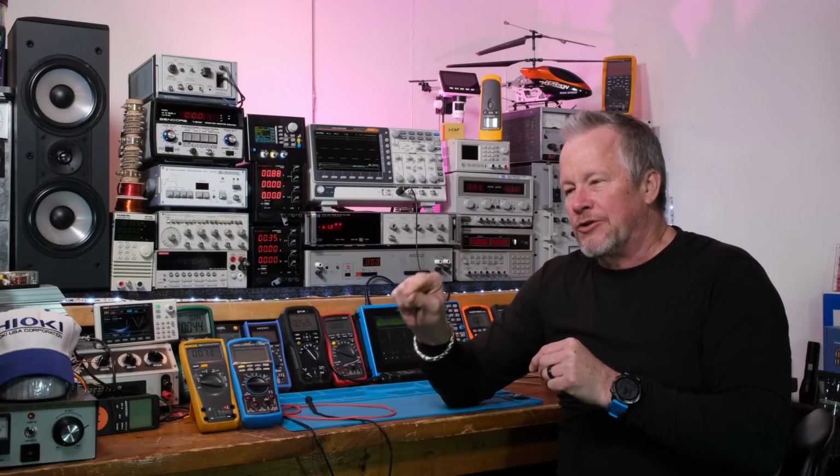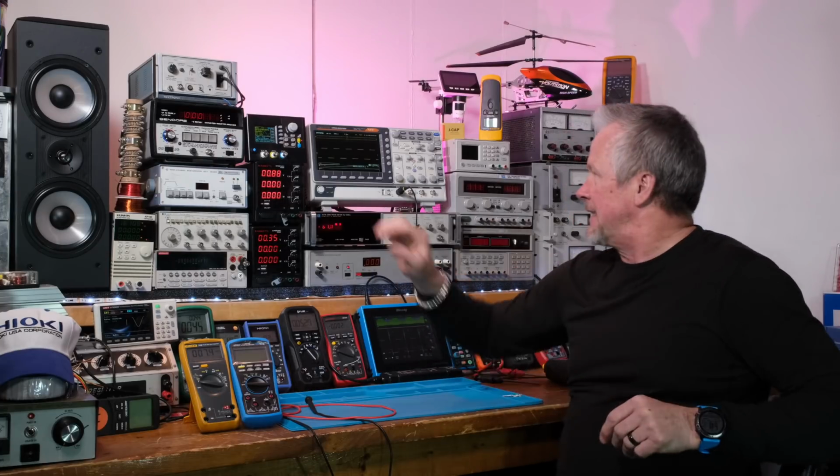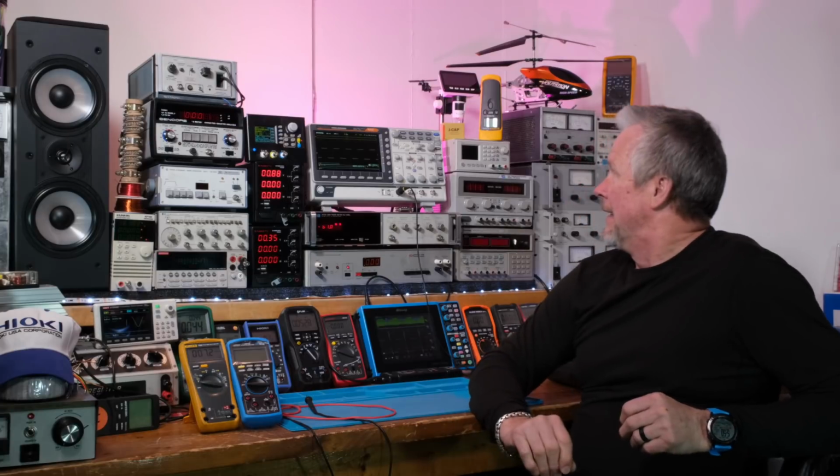Say you accidentally put it on the 5-volt output, it'd short that 5 volts to chassis because over here it's tied to chassis. So some people will float their scope so that doesn't happen. And maybe it's safer for the scope, maybe not safer for the person. So it's not recommended practice, but people do that.